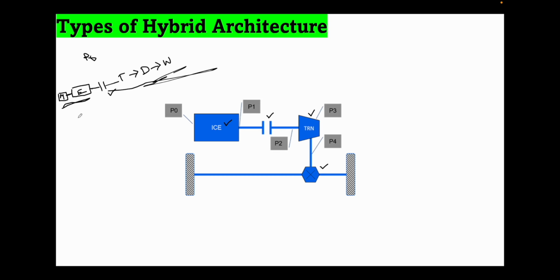Here you can see there is no possibility of having only E mode, only motoring mode, because if you start the motor alone, then the engine will also rotate. Because of this, only motoring mode is not possible in this case. But engine-only mode is possible, because the motor shaft will be free when you do not give any current to the motor, and in this case the engine can rotate, and you will get the output through the transmission and the differential to the wheels.